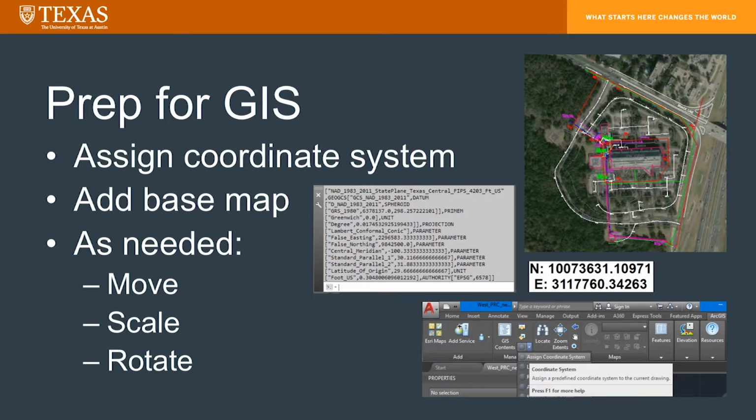Resave it back to whatever version will be able to read it. Another tip to tell whether your ArcGIS version is able to read the CAD version: when you bring it in and zoom to the layer, if you see a blank screen, that's a really good indication that the AutoCAD drawing is not in the correct version.